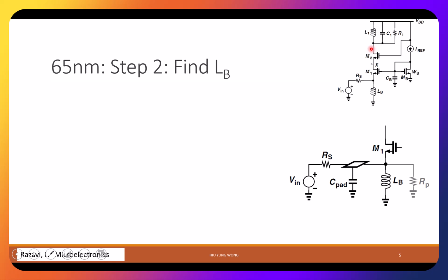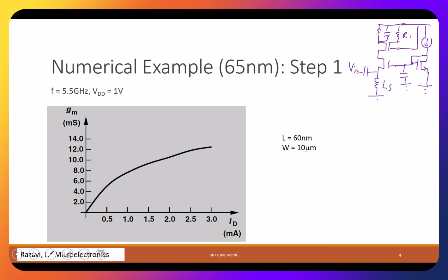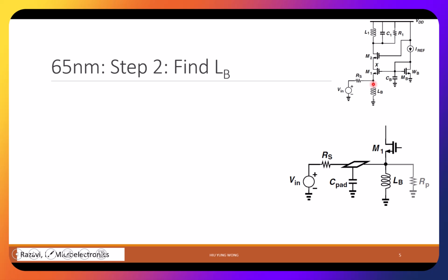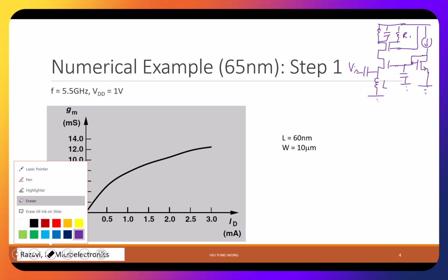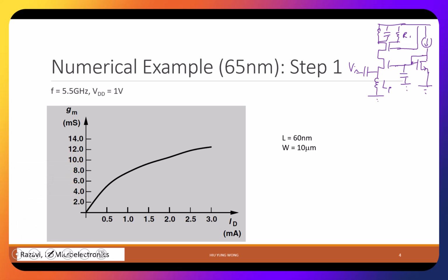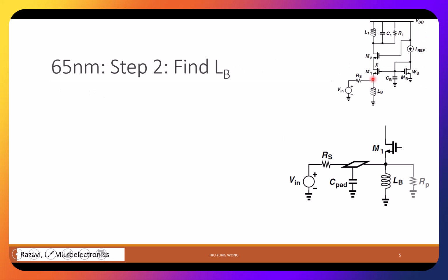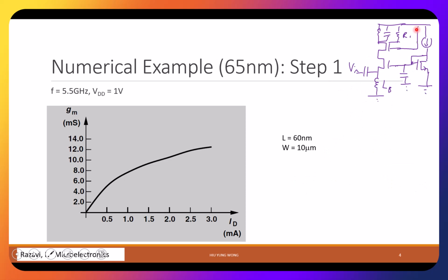VL is here, yeah? Common gate, right? Oh, I made one mistake already. I keep saying that is common source. Common gate, of course. I put the gate at constant, right? So this is called VB, not VS as in the other slide. But I just want to show you that if you understand all the keywords, I also can draw it without a cheat sheet, right? Cascode, and then reference. I also put, yeah, it's correct. I put it at the right place, although I draw it directly to the VDD.